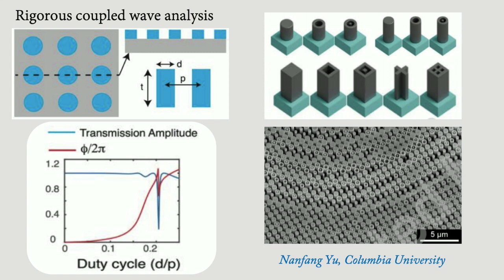It really brings diffractive optics to an extreme scale where you are doing this sub-wavelength engineering. The reason it's possible today is because we have the fabrication technology of fabricating these structures. Okay? Just going to remind you, we're talking about sub-wavelength. So for visible wavelength, the sub-wavelength is less than 400 nanometer, or let's say less than 600 nanometer. That's very small structures, which we could not fabricate, let's say, 20 years back. And these simulations that we are running are extremely computationally expensive, but the computation is almost free today, so we can do that.